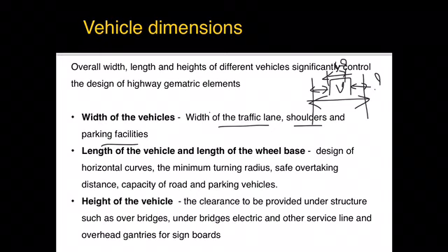The length of the vehicle is required whenever you design horizontal curves, at the places of curves, to decide what radius you have to provide. Also, the overtaking distance required during overtaking operations, and the parking of your vehicle. Similarly to how the width is important, when you fix any parking space, we have to look into the length of the vehicles also.